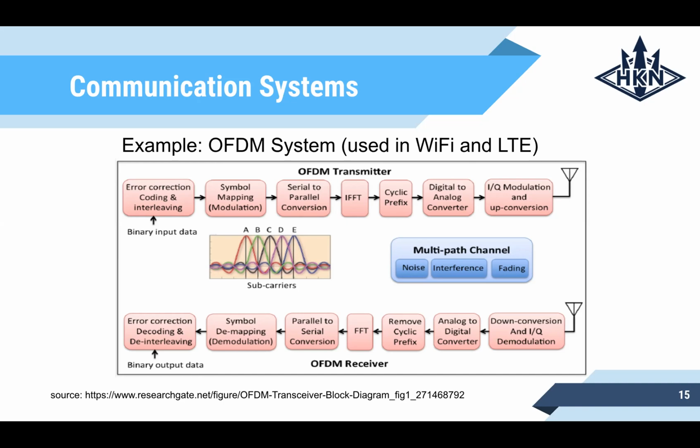So modulation is essentially taking a carrier signal, like a sine wave, and varying its properties to embed information. One example of this is amplitude shift keying, where the transmitted waveform is high when we want to send a 1 and low when we want to send a 0. And all of this modulation stuff is pretty low level, because we're looking at the actual waveform that's physically transmitted across the channel. On the other hand, we have coding, which is more of a high-level field.